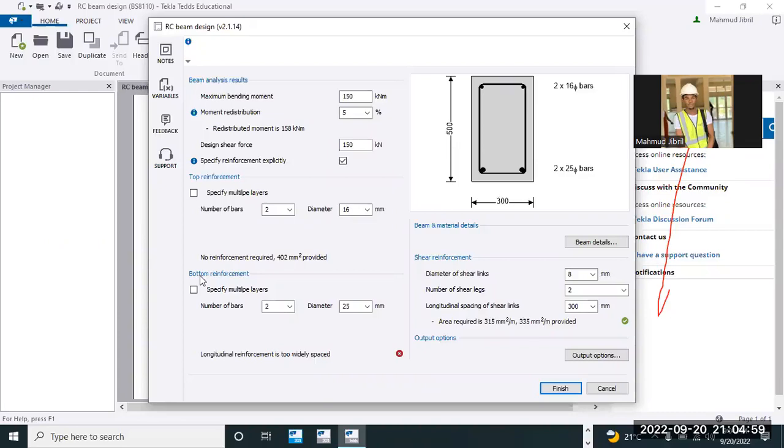A flange section is more economical than a rectangular section. If it is a flanged section, assume a T-beam or L-section, it might be just 4Y16 or 5Y16. Because it is a rectangular section, you might have too much reinforcement at that position. And then I am going to go with Y16.